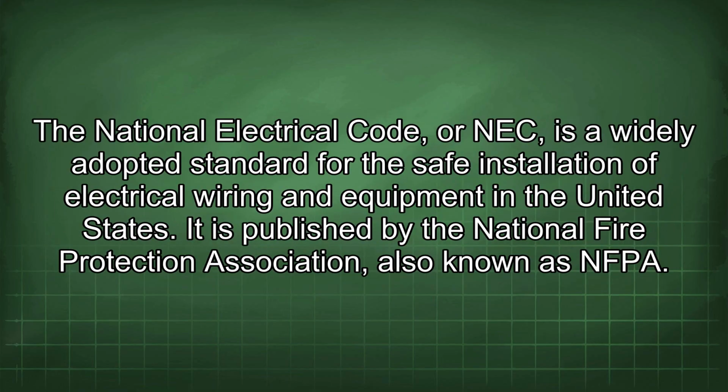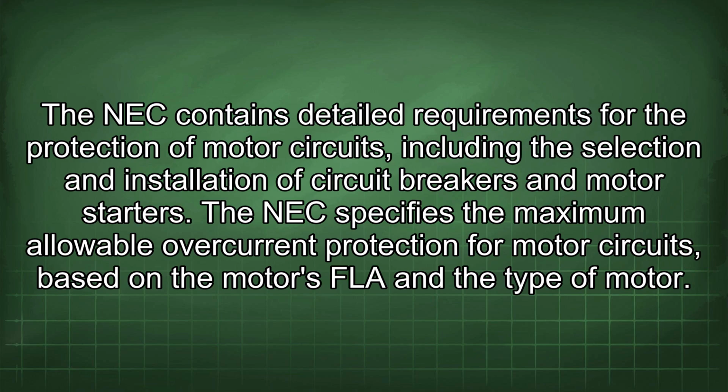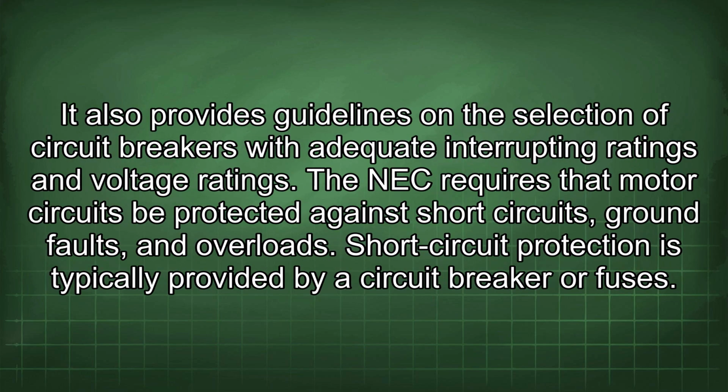The National Electrical Code, or NEC, is a widely adopted standard for the safe installation of electrical wiring and equipment in the United States. It is published by the National Fire Protection Association, also known as NFPA. The NEC contains detailed requirements for the protection of motor circuits, including the selection and installation of circuit breakers and motor starters. The NEC specifies the maximum allowable overcurrent protection for motor circuits based on the motor's FLA and the type of motor. It also provides guidelines on the selection of circuit breakers with adequate interrupting ratings and voltage ratings.